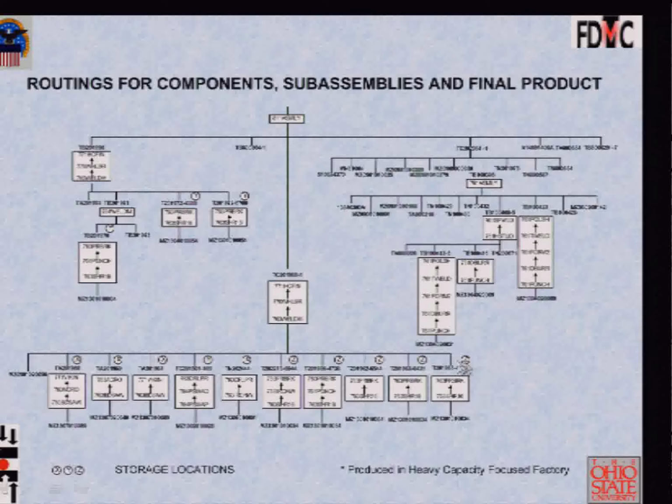You know, look here again. When you notice these individual components being produced, they do not necessarily end at the same machine, the same work center, right? This is press brake, then there's a wheelabrator, then there's some iron horse, there's some other machine, right? There's a Viking. Why are these parts being delivered to different locations? Now, it could be there was a lack of space, but then the point again is that if all of these components should arrive at the MIG welder, why are they being shown as being stored in separate locations? So maybe there was a reason, maybe there isn't, but that's another thing to pick up,